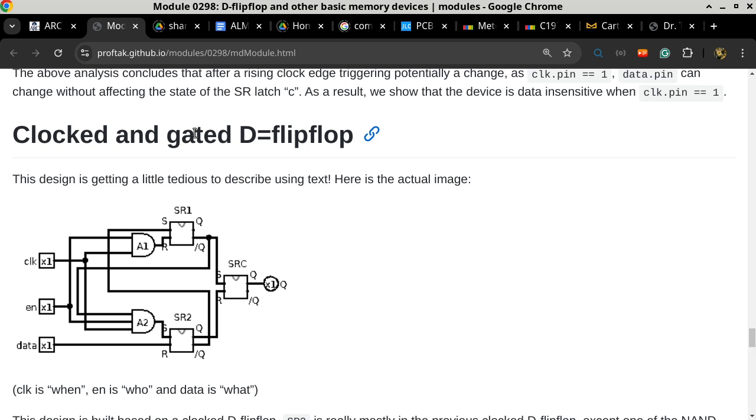Are we doing okay so far with this? Based on the description, you can give yourself an exercise of going through the whole thing. Let's assume all the pins are unknown to begin with, and you change all of these to zeros initially. Then the first one you change from a 0 to 1 is the EN, and then you change your clock from a 0 to a 1, which creates the edge.